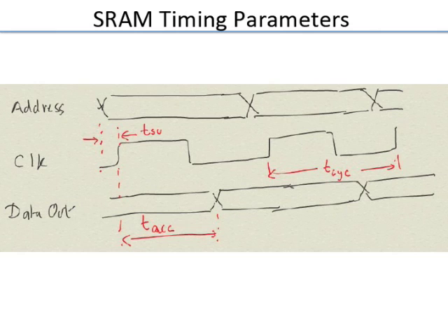That is right. So when we pipeline the SRAM, again internally, you could have the SRAM broken up into, usually, a two-stage pipeline. So internally you might have to insert one more pipe stage, which is triggered by this clock. So that could be one way.